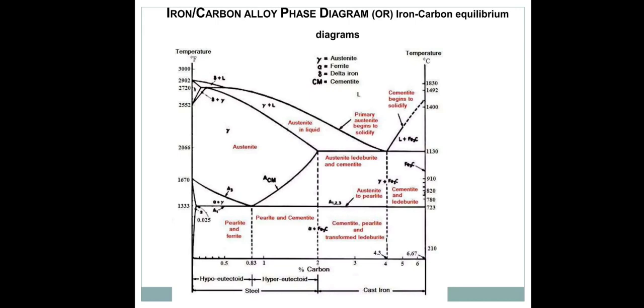It has very hard, more brittle, and low ductile properties. There is an increase in specific volume during formation of martensite from austenite. As a result, internal stresses are set up in the material, leading to the formation of micro cracks.